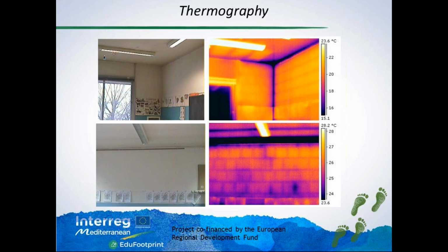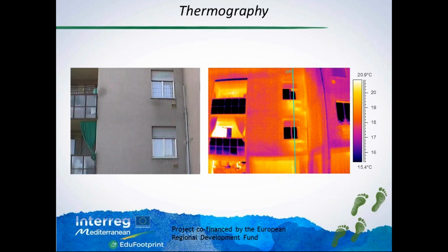So here in the picture, those are two pictures from inside, and it's clear how the corner here is a thermal bridge. It's a geometrical thermal bridge, but the effect is very important, and this is a real weak point of the structure, because there is the possibility to have some spores, and for a school this is not good. And here you can see also from the construction of the wall a very irregular distribution, and also some holes which can increase the transmission and the heating losses.